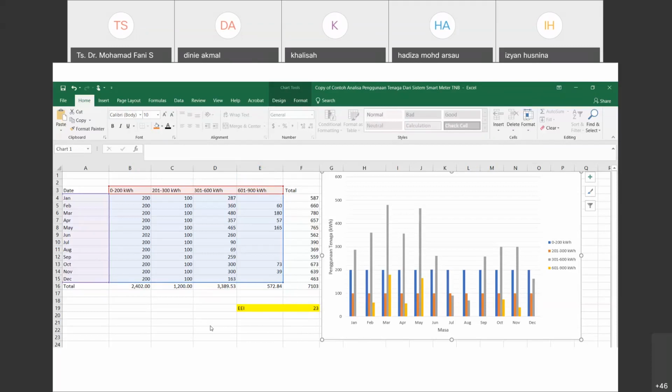So when you get the information in square feet, change it to square meters. In order to get the home energy index or home efficiency index, take the total kilowatt hours for the 12 months of data that you have, over the area of the home.